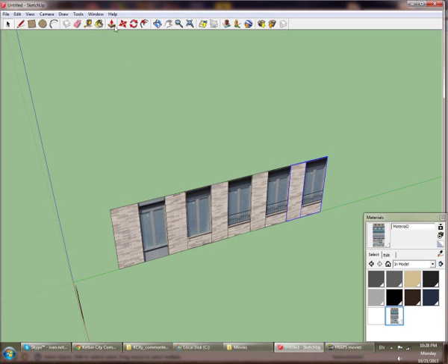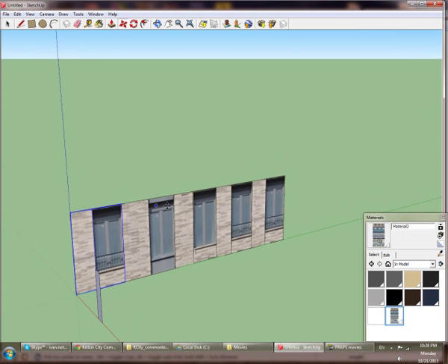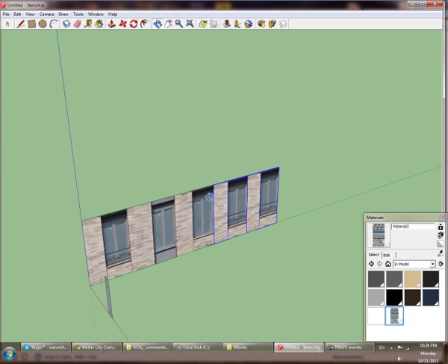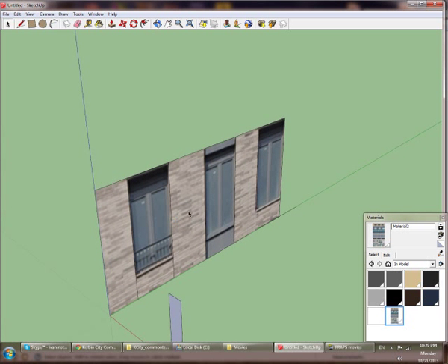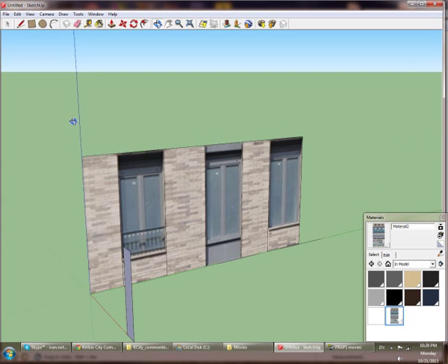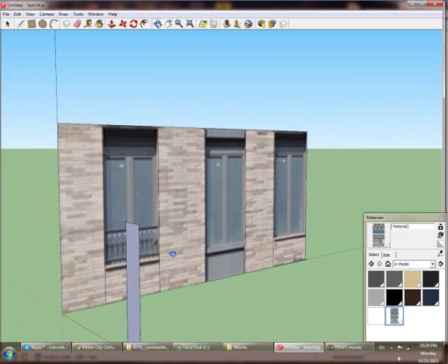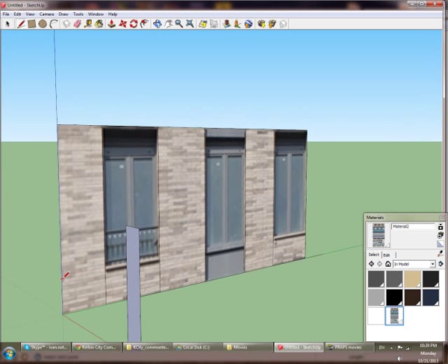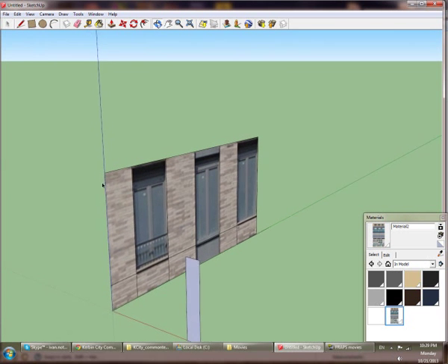And if I want to repeat the same thing I did yesterday with extruding walls in SketchUp, it's even simpler, of course, because you can use the push-pull tool. Oh no. For now I'm going to explode them, and I'm going to use the, oh yeah, I need to cut the windows first. And yeah, I think it's much better this time to cut the whole thing, so I have quads everywhere and I don't need to think about these stray edges.